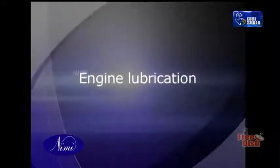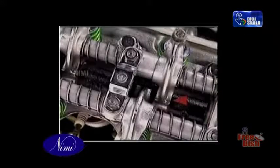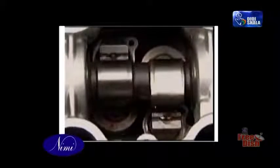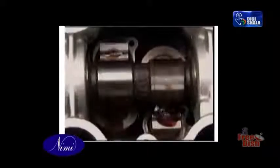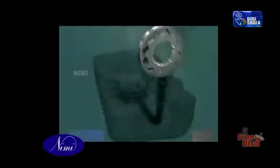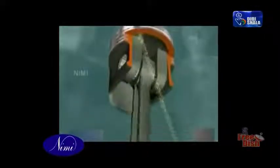Engine lubrication. The friction between two surfaces rubbing together is reduced by using a lubricant to separate the materials. A flow of oil used for this purpose can also be used to carry away excess heat from the metal parts. The majority of the engines are wet sump system in which the engine sump acts as the reservoir. The friction between the engine components is reduced by boundary lubrication, which relies on oil being splashed up on the surfaces.